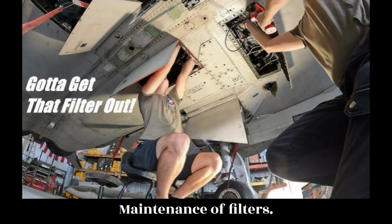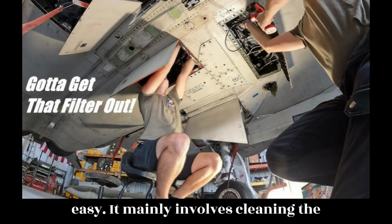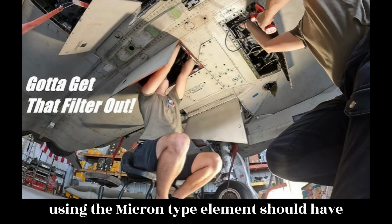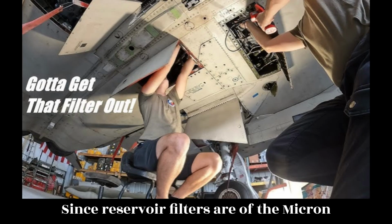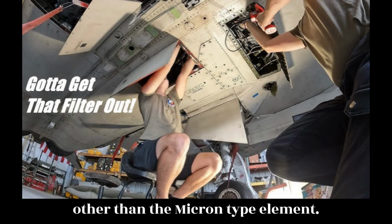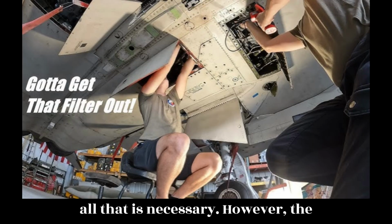Maintenance of filters. Maintenance of filters is relatively easy. It mainly involves cleaning the filter and element or cleaning the filter and replacing the element. Filters using the micron-type element should have the element replaced periodically according to applicable instructions. Since reservoir filters are of the micron type, they must also be periodically changed or cleaned. For filters using other than the micron-type element, cleaning the filter and element is usually all that is necessary.